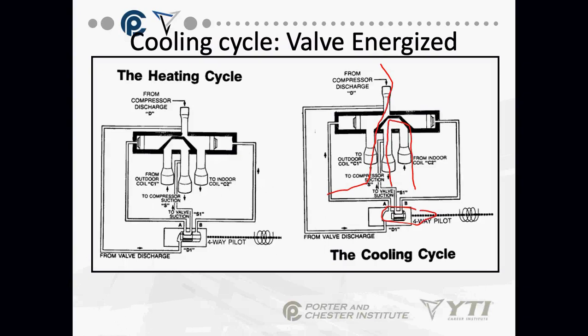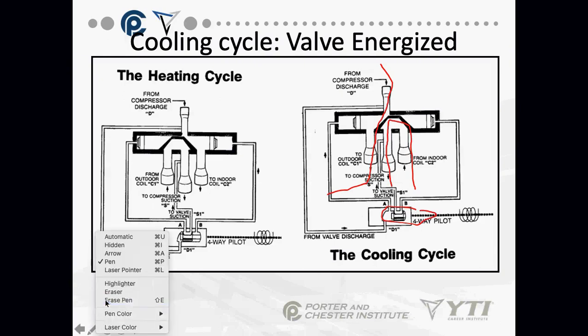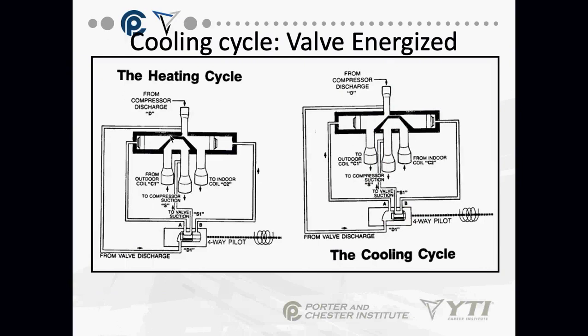So these are the 2 positions when you look at this slide of the reversing valve. Heating cycle de-energized, most often in the newer systems. Cooling cycle energized. And this is sometimes a pretty noisy energized thing. In my system, I can hear it down the driveway when that reversing valve energizes before the system goes on. It goes clunk, and you hear it start up.